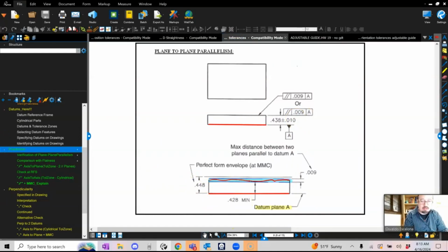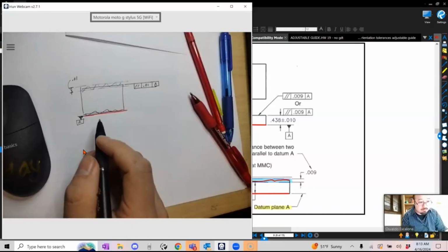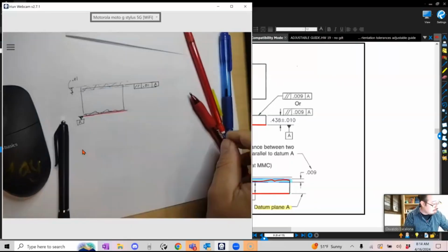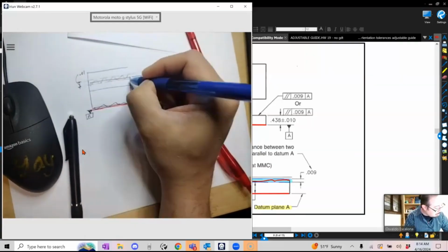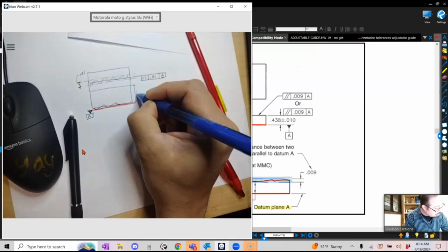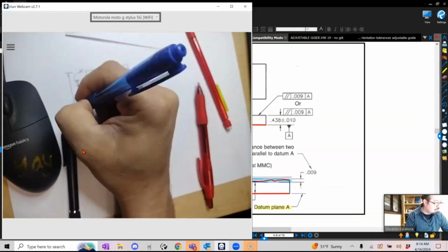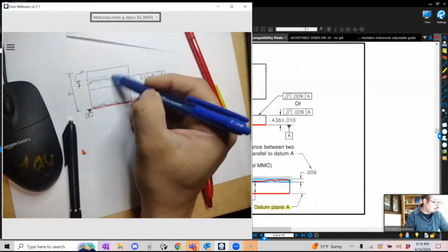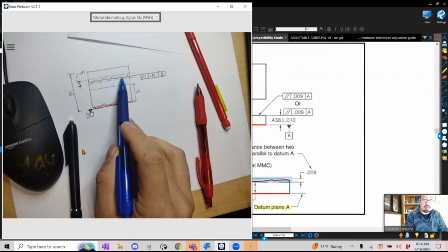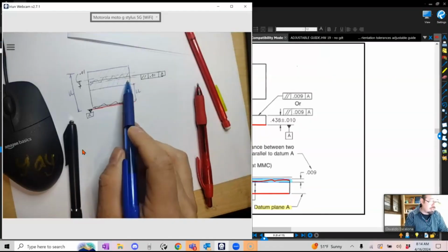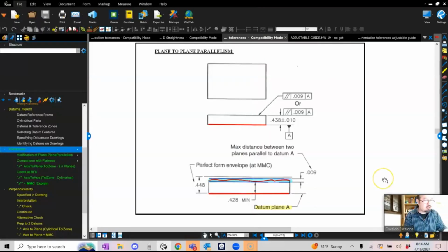So remember that you have a size tolerance and you have a geometric tolerance. Let's say that the size tolerance is maybe here, and the upper one is somewhere there. So from here to here will be the lower limit, right? And from here to there will be the upper limit, right? And my tolerance zone is this blue, but within the tolerance zone, I have another geometric constraint. This tolerance zone will live within this other tolerance zone, and I can move up and down anywhere within that tolerance zone. So this is pretty much what you guys are seeing here.